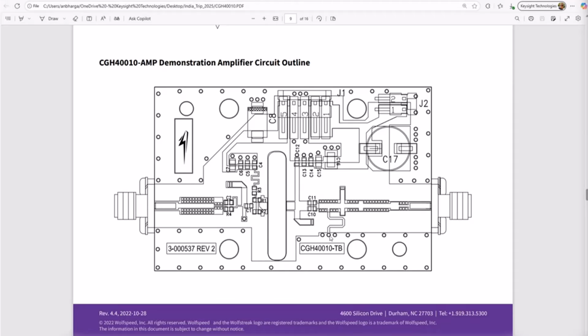You need to ensure that you have sufficient via holes right at the point where you're short circuiting anything. So whether it is a capacitor, notice here are the shunt capacitors, and you can notice one via hole right at the end of that capacitor, because you should not place these via holes far away from that component, because you don't want any inductive loop to get formed.